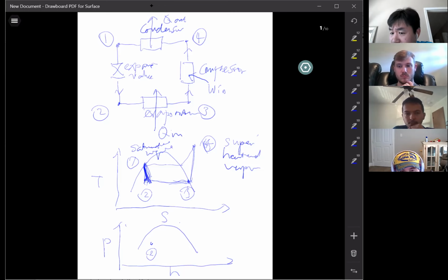The pressure in the heat exchanger is going to be the same. That's right. You just receive some heat, it won't increase your pressure, right? Okay. So the pressure should be the same going through the evaporator, although the phase changes, on the saturated line.